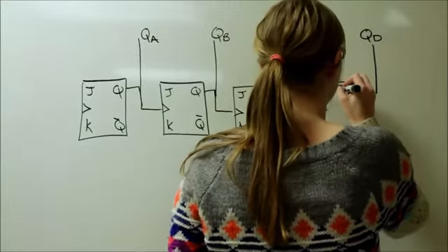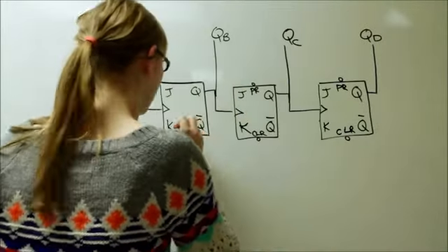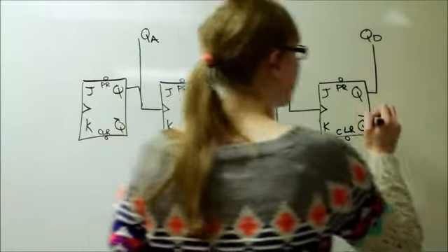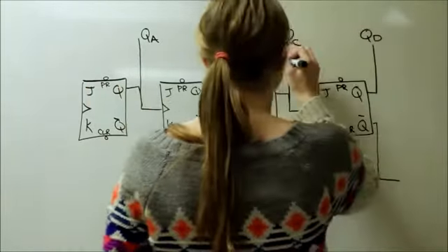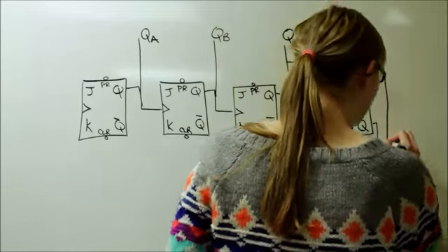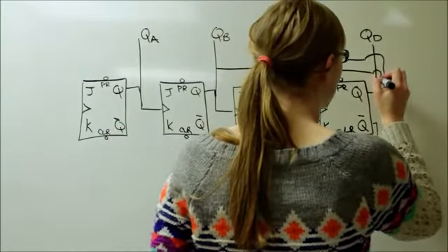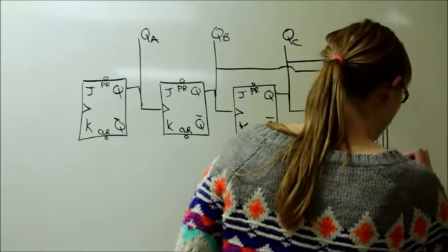In this counter, there are also preset and clear buttons. The preset button is left unconnected and left in a high state, but it is only triggered on a low, designated by the circles above it. Therefore, in this circuit, the preset will never be triggered.